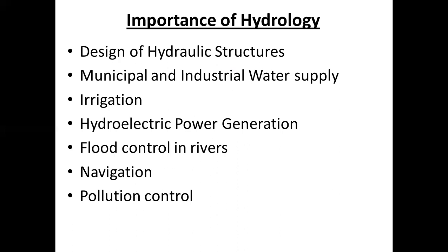Okay, so the next point is navigation. Navigation, specifically inland navigation. In this, the depth of the water should be maintained at a constant level, and this can be achieved by providing proper gates and proper draft, that is, extra depth should be maintained.